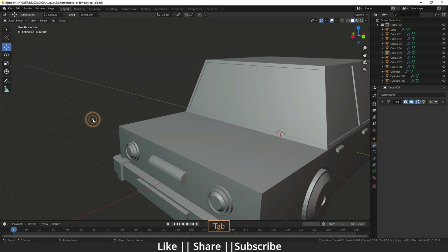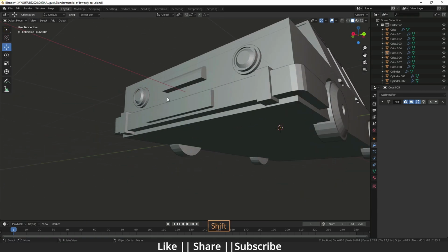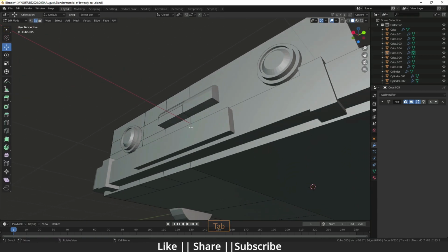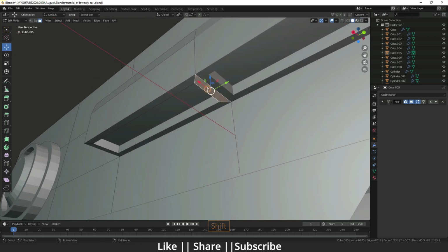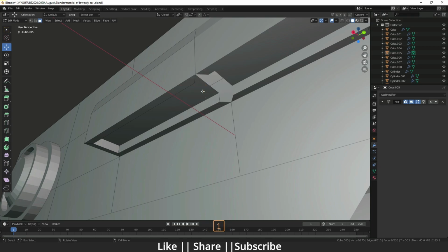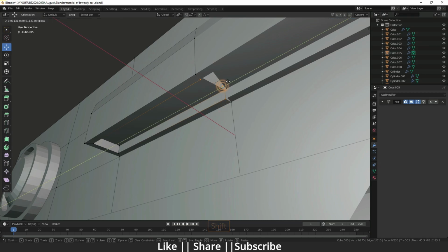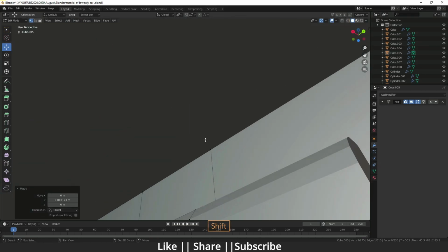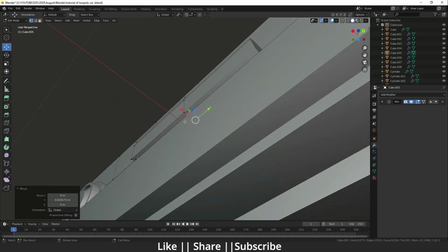Here you can see, and I will do the same thing here. Do an inset first, then extrude inside, and we have to delete that face and that face. Then we just select those vertices and do like that, and we have one vertex left.